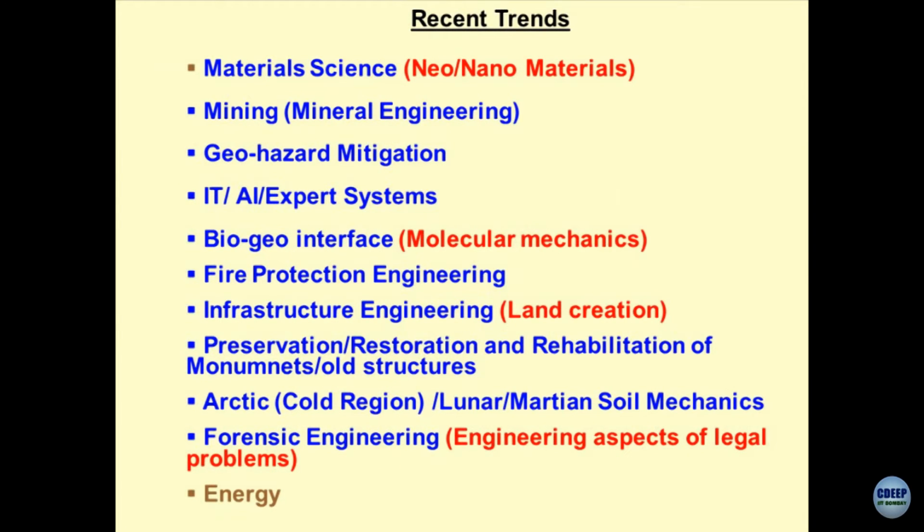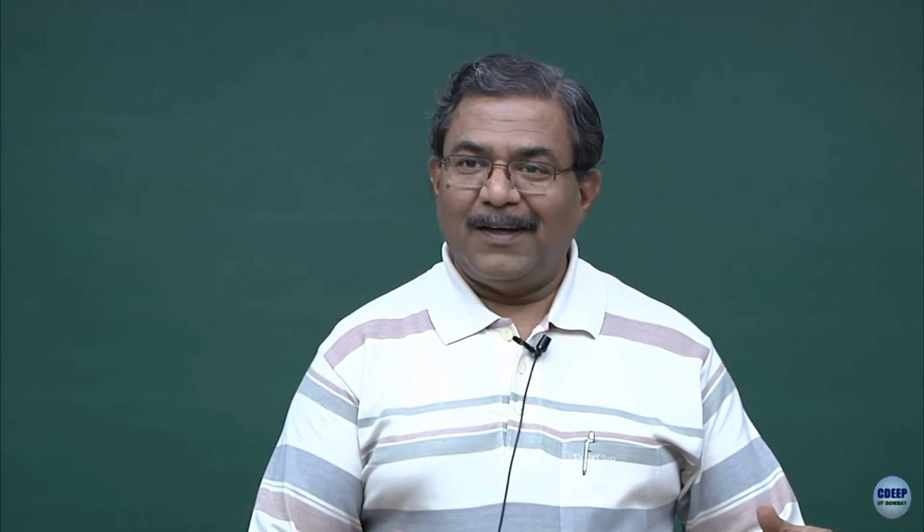We have done fundamental studies of how soils react to a microbial attack, and the whole PhD is done to quantify this process, to understand what type of alterations systems undergo when the bacterial or microbial activities attack the geomaterials. This process happens in nature, and it is so sad that very conveniently geotechnical engineering people have forgotten about this. So, normally what we do is we bring the samples from the field, we put them in the oven and we create a different type of soil which never exists in the field.